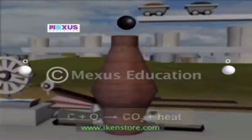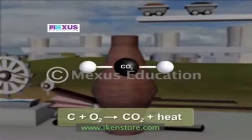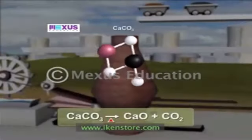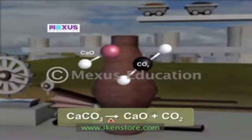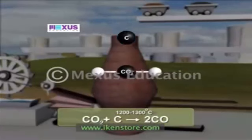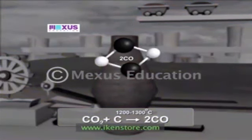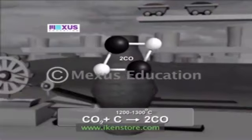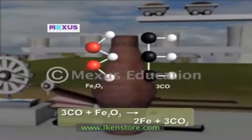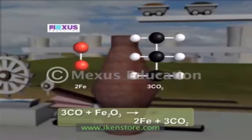The air passes upward through the charge where coke is burned to form carbon dioxide and heat. The heat decomposes limestone into calcium oxide and additional carbon dioxide. Carbon dioxide oxidizes coke to form carbon monoxide at a high temperature of 1200 to 1300 degrees Celsius. The carbon monoxide then reduces the ore to iron, taking on oxygen and reverting to carbon dioxide.